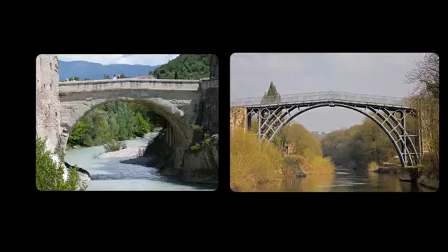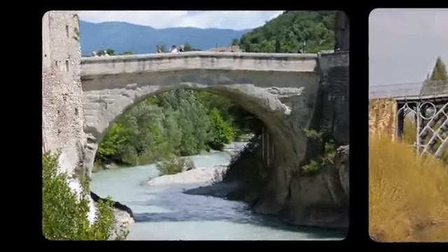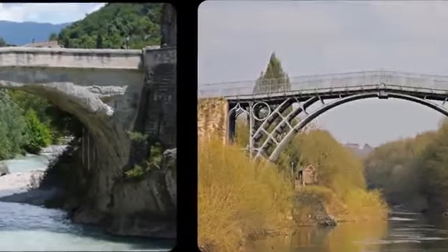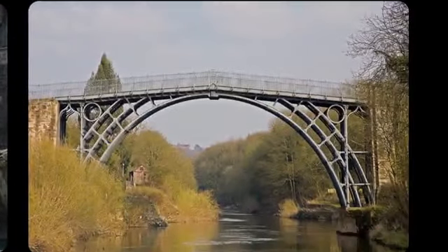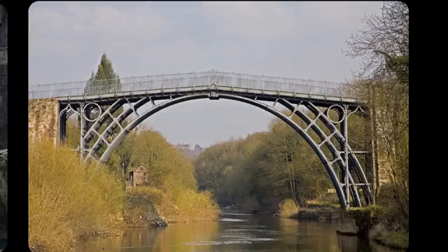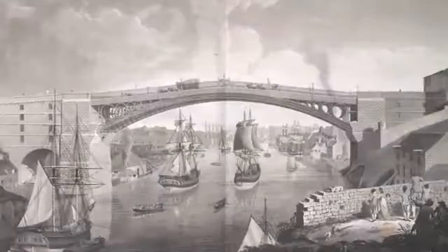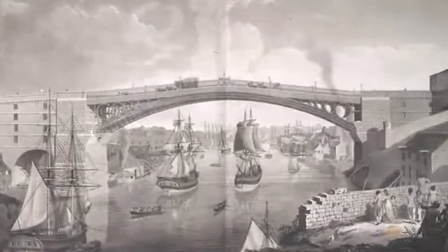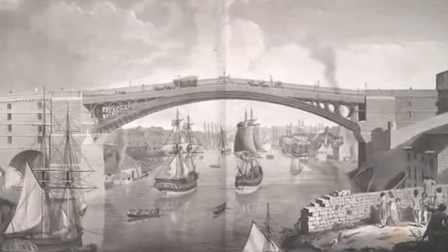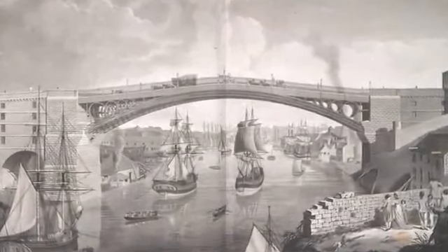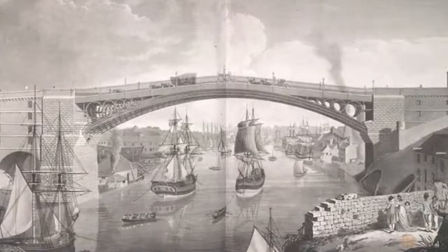The answer to the question is a stone bridge will be heavier than a cast iron bridge. Although cast iron is heavier than stone by volume, it's also much stronger than stone. Therefore, one can use much less material to build an arch. The resulting iron arch is much lighter than a stone arch. For example, for the bridge built by Rowland Burdon Esquire over the River Wear at Sunderland, an iron arch was estimated to be 15 times lighter than a stone arch of similar size.